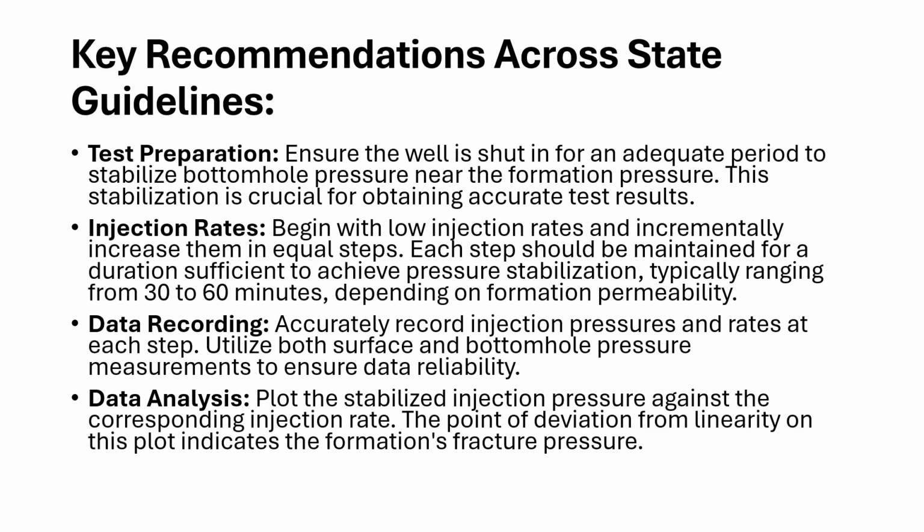So I've surveyed several state guidelines that are available online, and these are the key recommendations across those. The test should be done in preparation, and I would recommend that you ensure that the well is shut in for an adequate period to stabilize bottom hole pressure near that of the formation pressure. The stabilization is crucial for obtaining accurate results. Begin with low enough injection rates and increase them in equal steps. Each step should be maintained for sufficient time to achieve pressure stabilization. And these range from 30 to 60 minutes, depending again on formation permeability.